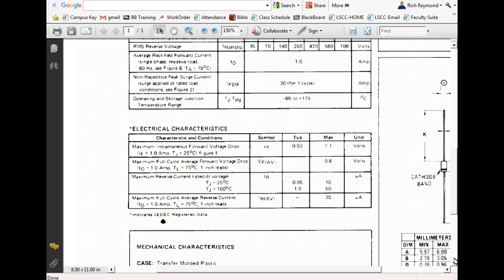The traces on the circuit cards are a lot easier to dissipate the heat than the leads. Also, the traces on the circuit cards are usually copper. The leads on the diodes are copper plated, usually with nickel or tin. And why do they plate the copper leads on the diodes? When you look at your diodes, they're not nice and orange or brass colored like copper. They're silver. And why is that? Why do they plate them?